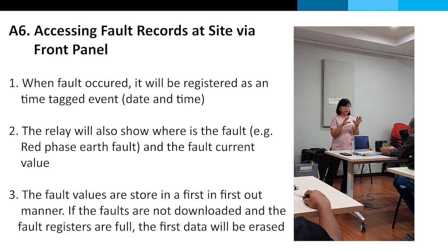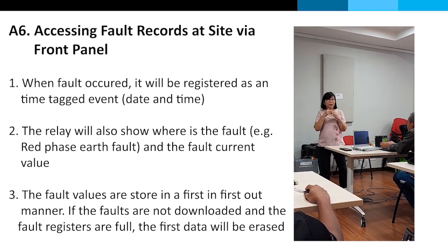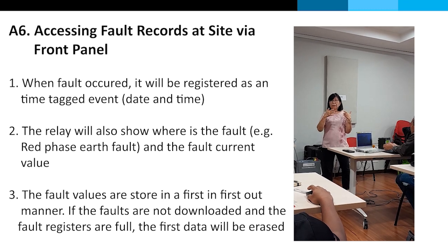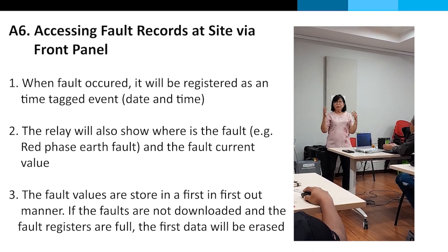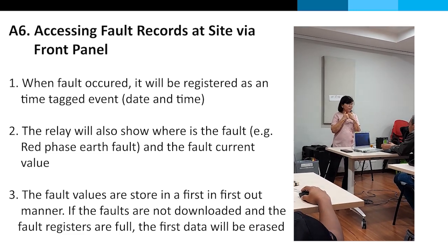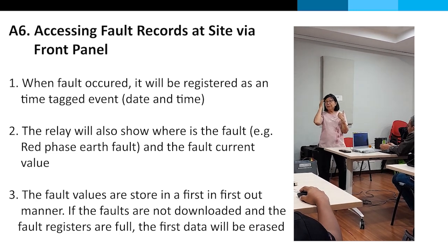Okay, so you can go to the relay and press, and you see the faults that you have. Okay, first in, first out. If your register is full and you don't download the fault, you don't record the fault, then you will lose the first few records, right?